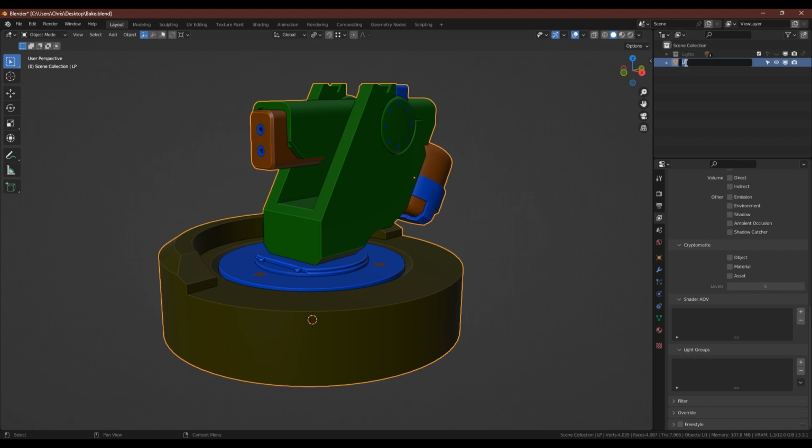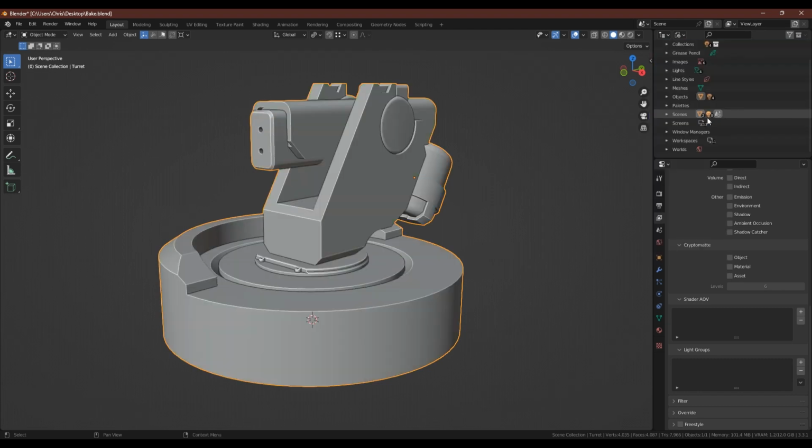Something else we can do is go into the Blender file and remove all the meshes apart from the one that's attached to the turret model, which is all of them apart from cylinder 004 in this case. These are all unused leftover geometry. Can do the same for the materials. Just remove all of the materials because we're going to start a new material. Just keeps the file nice and clean. Can delete everything out of the images as well, apart from the Machine Shop 02, which is the HDRI. And then just going to switch back to the view layer.